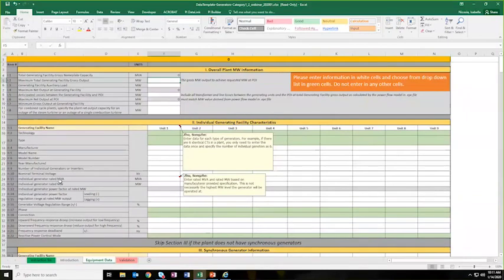Well, that was what we were flagged on, as I gave the 54 megawatts as being the total gross output, the maximum total gross output of the generator, and it's a 0.8 power factor, so the reactive capability at rated is quite a bit greater, but it's actually unachievable because the unit has an old amplidyne excitation system, and it goes unstable. Yeah. Tom, I know we received this question from you in writing as well.